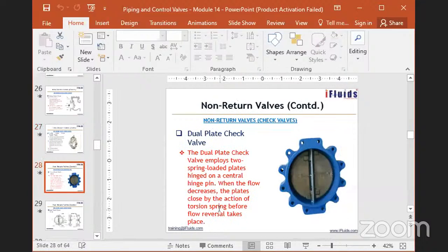Okay. Next question. What is a volume bottle? A volume bottle is a small vessel holding the instrument air. It will be under pressure and it will be connected to the valve diaphragm. And when the instrument air fails, the valve goes to a certain position, correct?